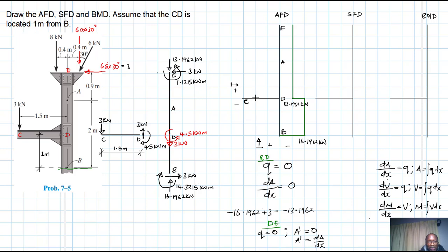the two are going to interact. What we have there at E, we have another value which is going in the opposite direction. So you know what happens, they'll add up algebraically. So we have a minus 13.1962 plus a 13.1962, which gives us a what? A 0. Therefore, a what? A closure. Right. So let's close this. I prefer my color. Let's close this. There we go. Great. This closed.